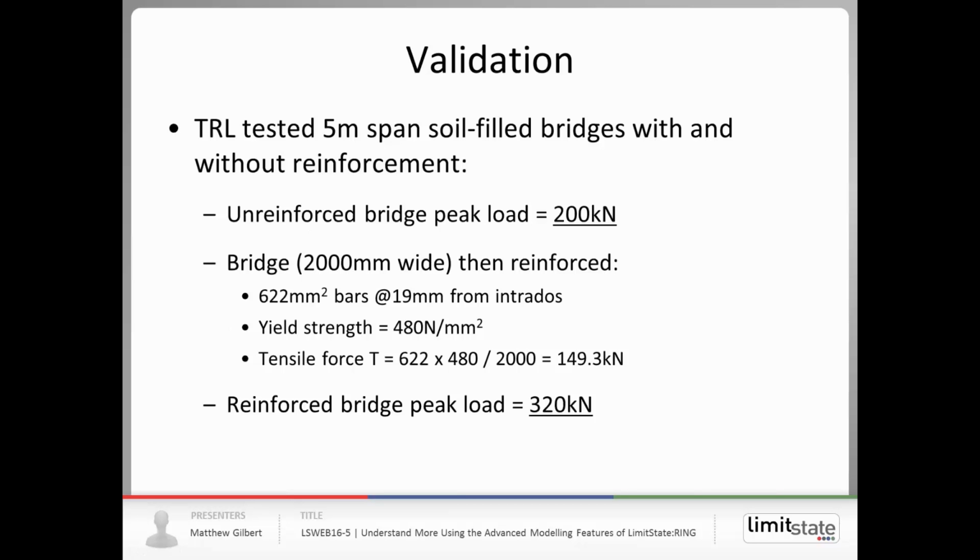There is a validation example in the literature. There's a 5-meter span soil-filled bridge, one of a number of soil-filled bridge examples tested by TRL some years ago. So they tested bridges with and without reinforcement. In this particular case, the reinforcement was steel reinforcement, so given area and yield strength gives a tensile force of 149 kilonewtons per meter width.